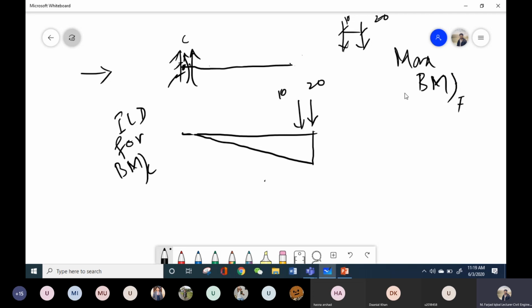So there is a small confusion that happens in the case of this cantilever beam when you are going to find the bending moment. You should look at the influence line diagram to figure out the location of the moving load. You have got the point. It is not the same for all cases that at the same point where we are getting the maximum moment, we have to place the moving load. We should look at the influence line diagram to figure out where we should place our moving load to get the maximum value of any function.